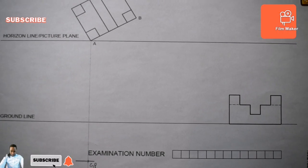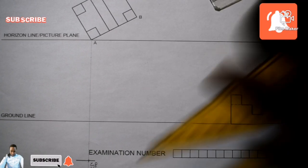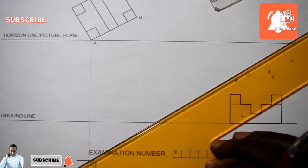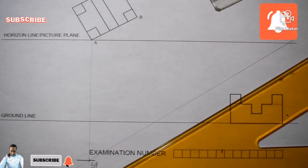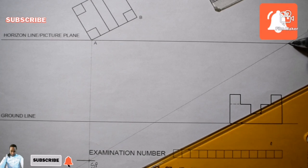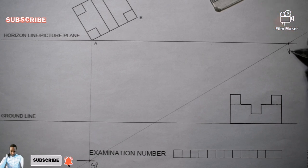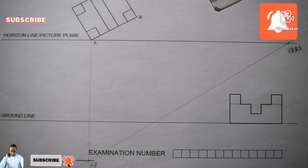Stationary point. You understand? So from there, I take this point at an angle of 30 degrees, point P. Draw it faint. Once it touches the horizontal line, the picture plane line, I stop there. I have a point right there. The name of that point is the vanishing point of my right hand side.